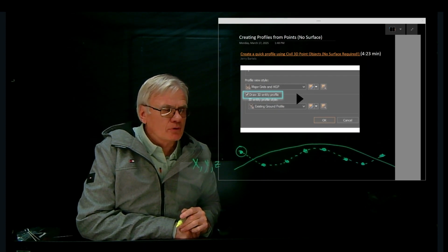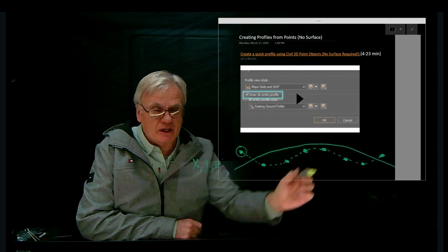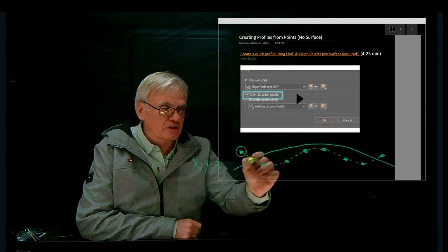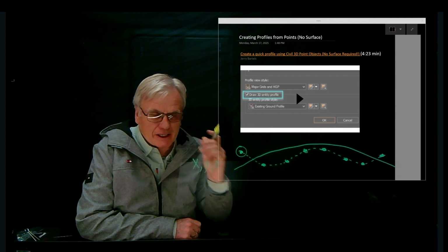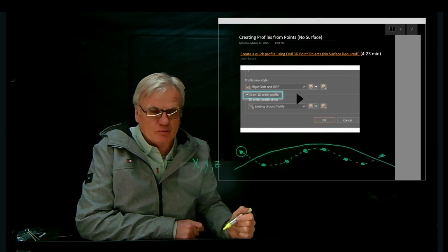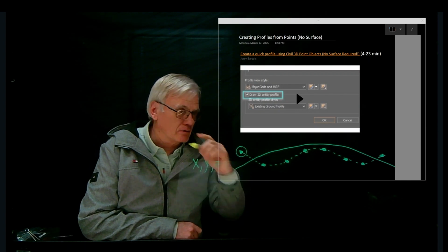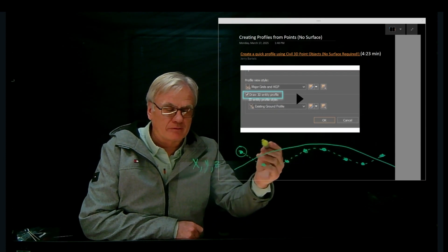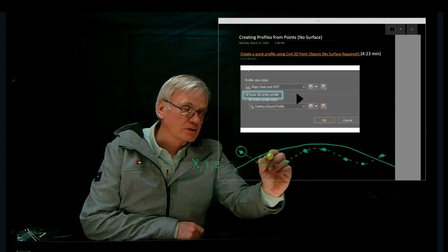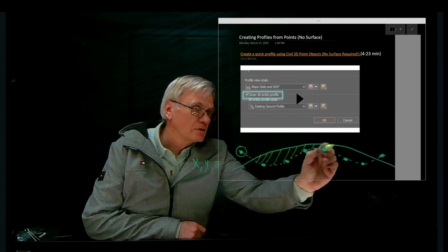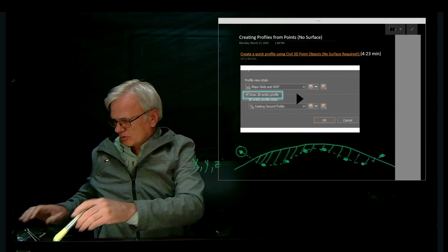So we can go ahead and do this and establish the existing terrain in Civil 3D. We can establish the vertical profile grade line, which is essentially, as I've drawn it, a curve through this terrain. And then we could have AutoCAD Civil 3D tell us the cut and fill along this, and we could do it quite quickly.